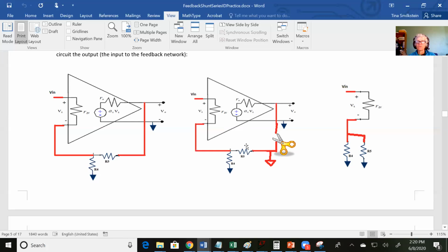But it turns out if you hook this up with resistors that are very small, or actually on the order of R pi, you end up with a voltage divider on your Vin. So your actual Rn looks like your regular Rn in series with these two feedback resistors. Okay, so Rn gets bigger.